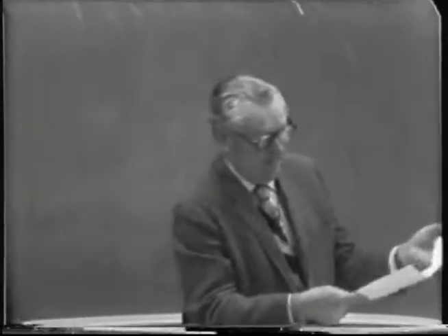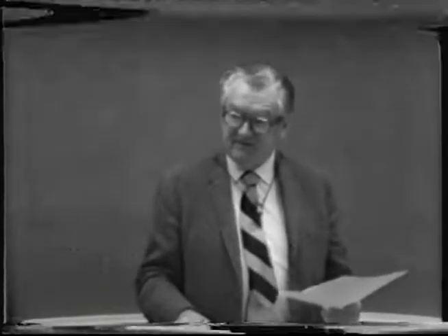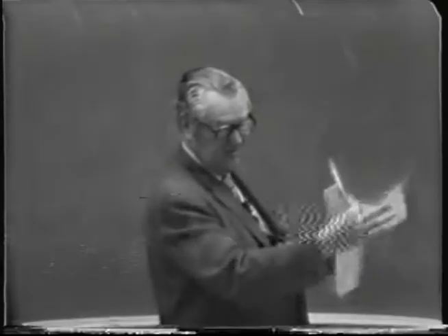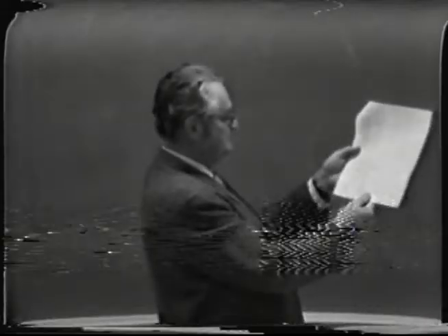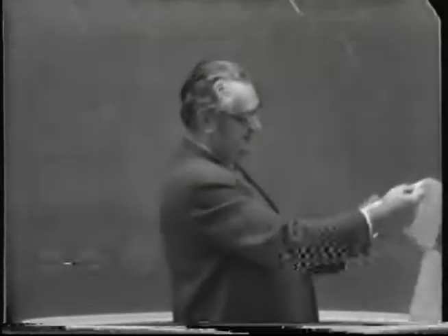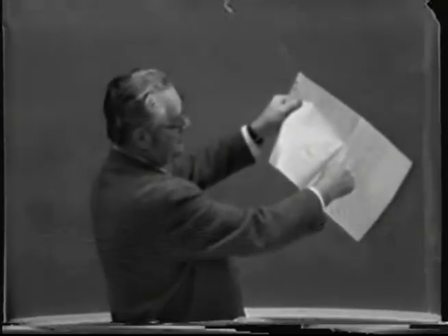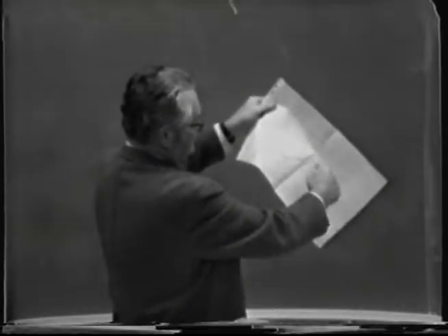The next part, of course, is to plot the equilibrium curve, which I did by simply taking our table of equilibrium data for ethyl alcohol and water and plotting sufficient points. You see, it comes out to be a straight line in the lower ranges of alcohol. Of course, up here it curves and becomes tangent. If I had completed that curve and had sufficient data up here in the upper part, past the azeotrope, we'd have had a line significantly above the curve. But I didn't plot that.